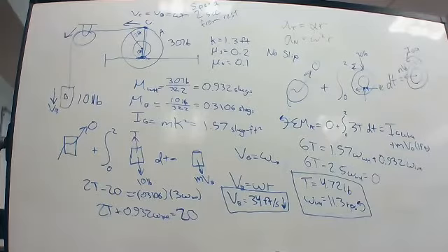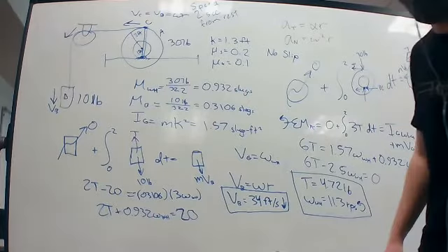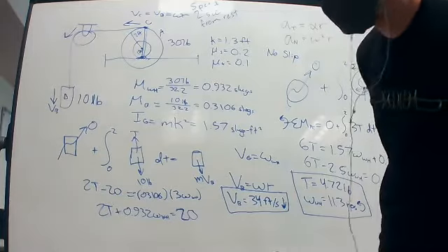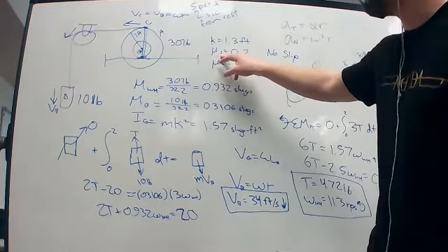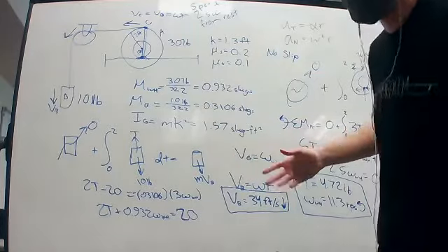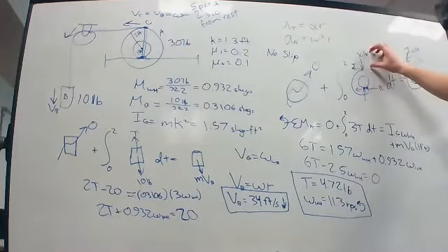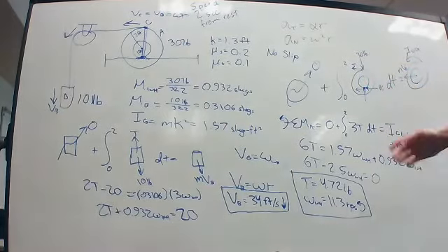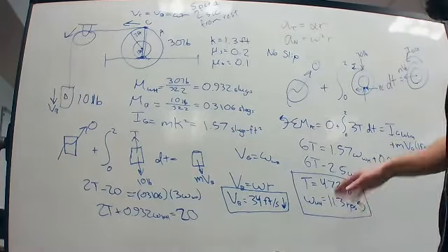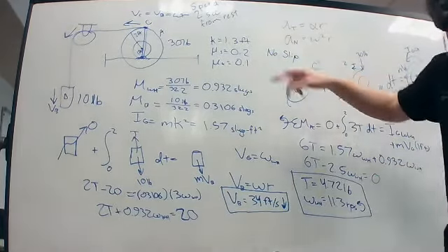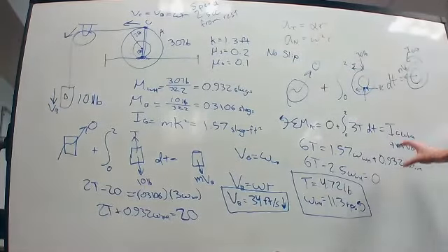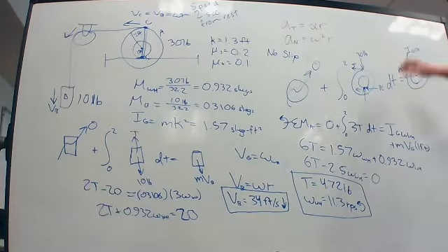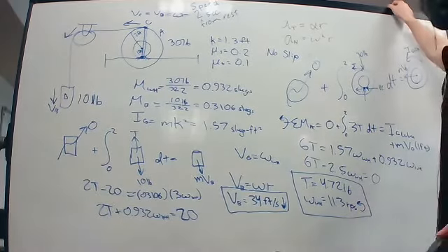Okay. And so as long as you do that, you can find the friction value by doing mu sub s times the normal force, which you know is just going to be the weight because these are the only two y direction forces acting here. So you would say friction is equal to mu sub s times n, where n is 30 and mu sub s is 0.2. That would be your friction value, and you would need to have that in your moment equation. Okay. All right, thanks. No problem. Any other questions before I erase?